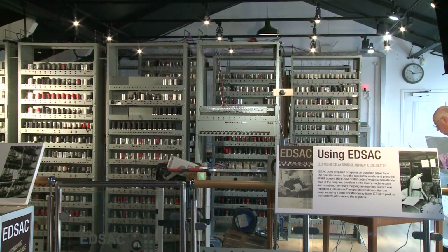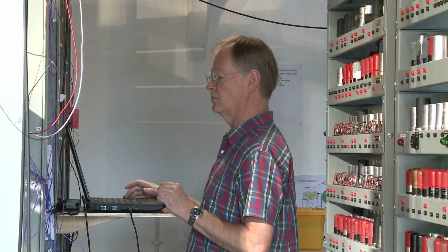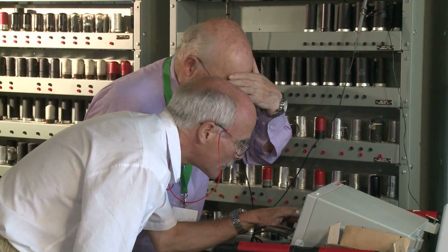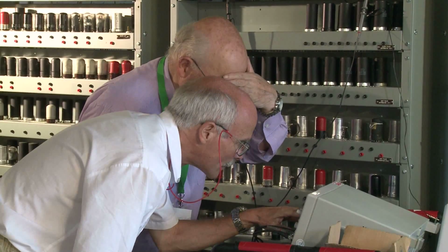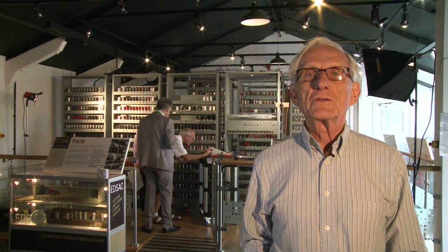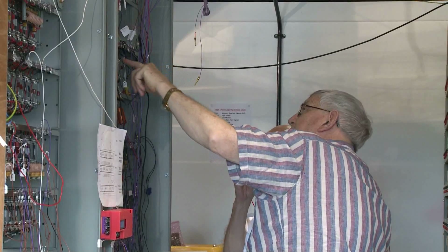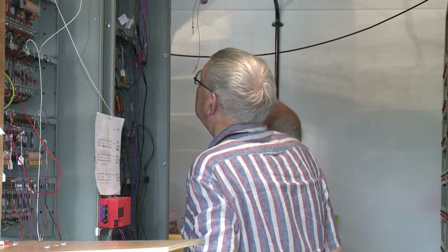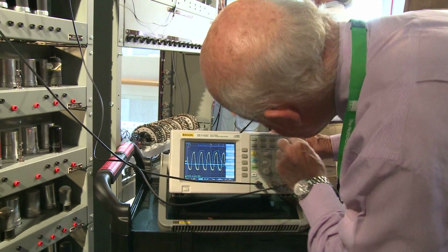We are in July 2016 in front of the EDSAC replica, when the commissioning work to get the machine working is reaching a very interesting stage, where we're attempting to integrate together some of the subunits which have already been tested individually. This integration part of the work is where we really get to grips with commissioning the whole system. Our current objective is to get an instruction working: to fetch an instruction from the store, decode it and execute it, and then get ready for the next instruction.